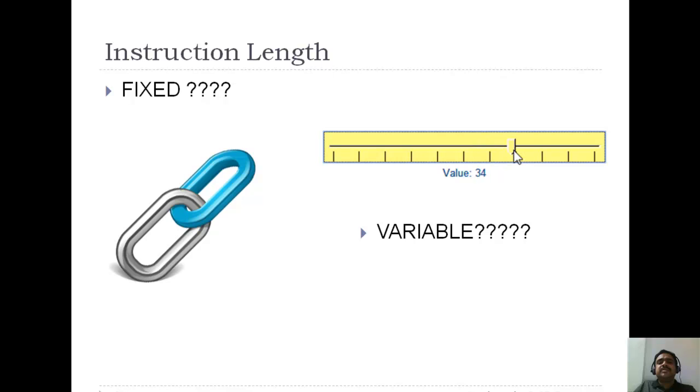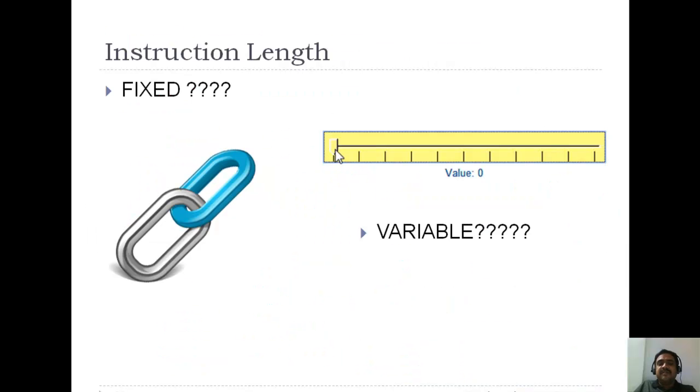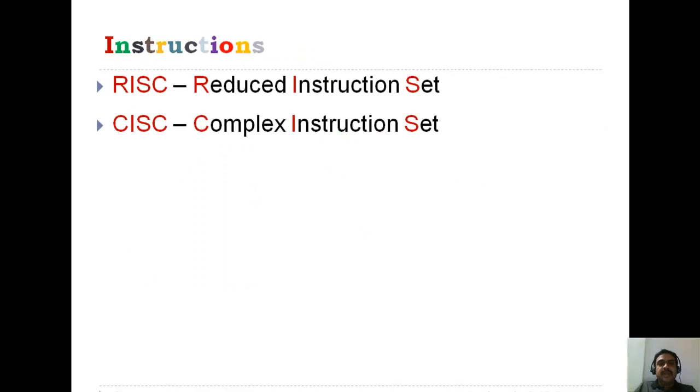But when it happens to be variable length, this is going to vary from instruction to instruction, data to data. So the decoding logic becomes very, very complex. You cannot just take the first 4 bits always for opcode. Sometimes it could be the first 2 bits, the MSB and the next bit to the MSB, could be for the opcode as well. So here the decoding logic is very complex. So this is the problem with variable length coding.